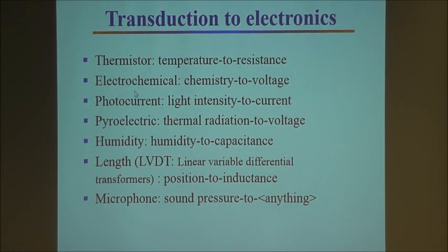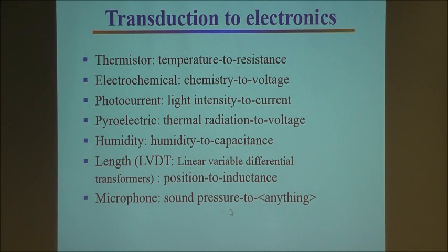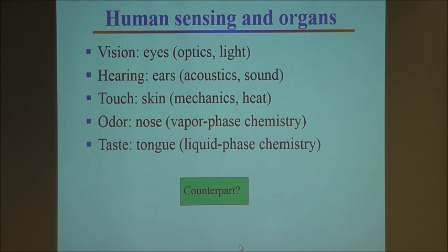Thermostat, temperature; electrochemical, chemistry to voltage; photocurrent, light intensity to current; pyroelectric, thermal radiation to voltage; humidity to capacitance; length, linear variable differential transformers, or position to inductance. And microphone, sound pressure to anything you like.